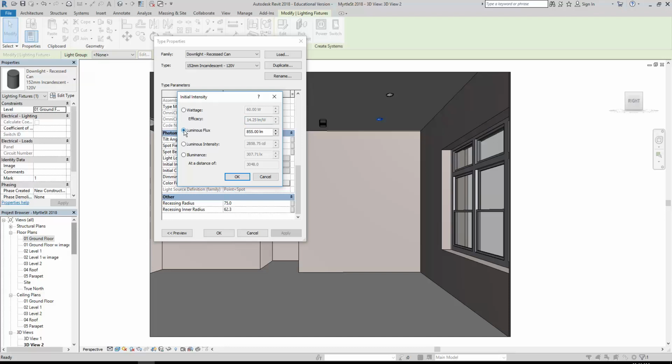What you want to think about is a single value that will tell you how bright the light is, and the standard these days is lumens. So this one, luminous flux, don't worry about what that means. Over here you can see it's on lumens, LM means lumens. To help me understand that, when I was first learning about lighting, I actually started with candelas, the one underneath. Candelas is just the older unit, the imperial one. That's the temperature, we'll get into that, that's different. Candelas are really easy to understand because a candela is the brightness of a candle, roughly.